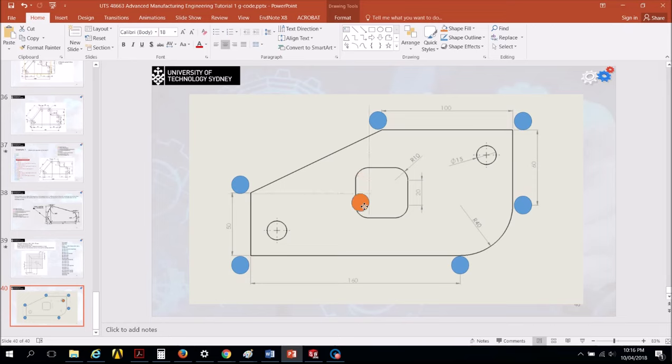I finish this one, I have to come to here now. I'll go to any point. Let's say I'm going to do the drilling here. If your cutting tool has a 20 millimeter diameter, I don't need to do any circular interpolation. But for example, if it's going to be a 5 millimeter radius, then I have to do point to point movement to do this pocketing process.